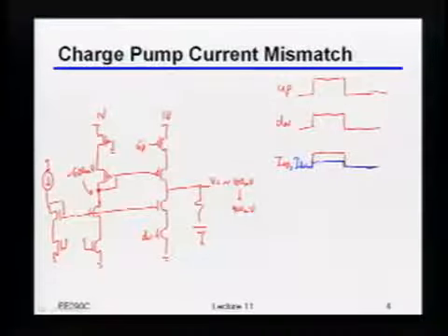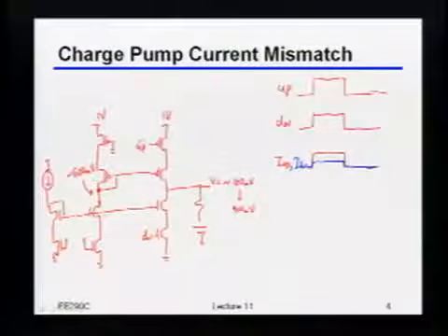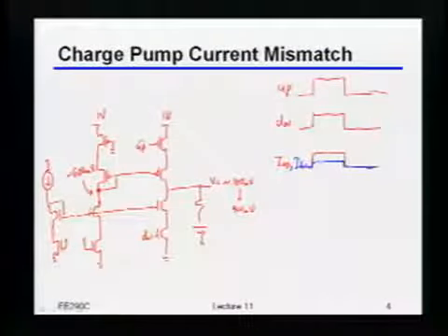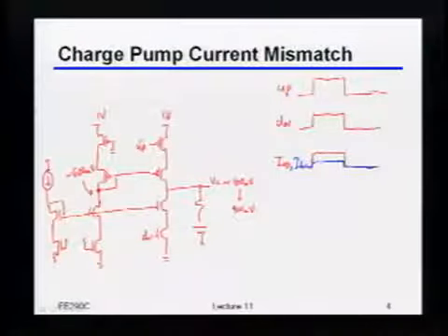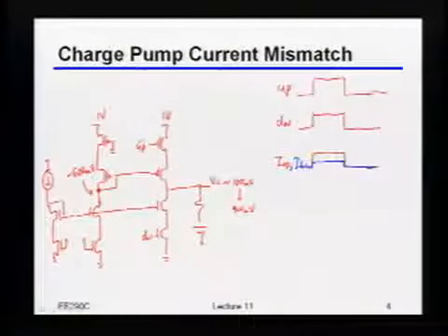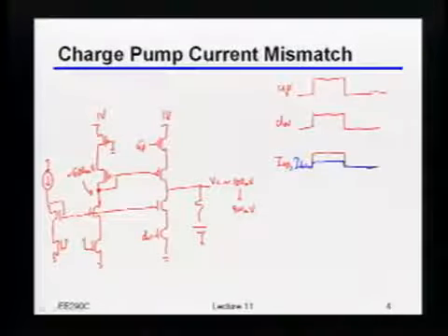Can it stay there? In other words, can it stay in this particular condition? It can't, right? Because even though you have a balanced phase input, you're pushing the control voltage up, which means you're increasing the frequency. Okay, so where do things have to land in steady state? Where are we going to end up? What's going to happen to balance things out? By the way, what is the balance point? How do you find the balance point?